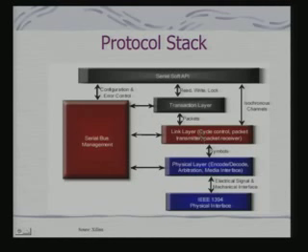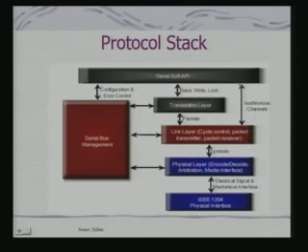Then you have a link layer, which controls the packet transmission and packet reception. This is a transaction layer which actually carries out the read-write transactions over the bus. And when it's an isochronous flow, which we had already discussed, that is media data delivery, they are not strictly read-write transactions. So under those circumstances, you really need the transaction layer to come into play. There would be direct transfer, and that transfer is managed by the link layer, and all these things through a serial bus management system.